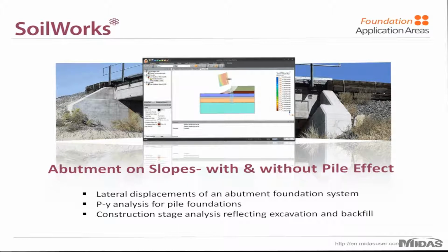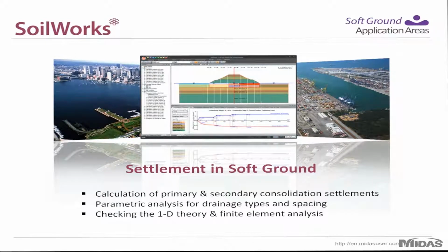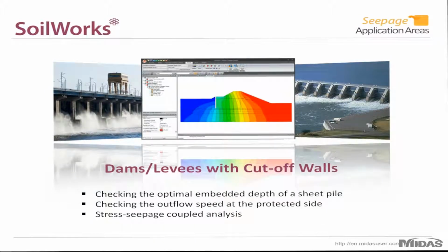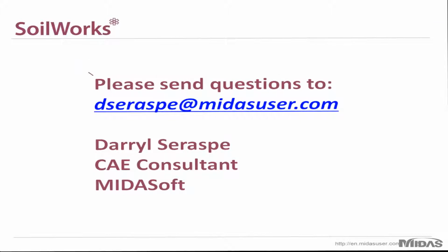Obviously using the foundation module. Abutments on slopes with and without pile effects. So once again, you can intuitively just compare the effects your piles will have on your slope. Group pile behavior, another function of the foundation module. Settlement in soft ground. Obviously, this is for the soft ground module, so you can analyze your consolidation of clay soils over an extended period of time. Dams and levees with cutoff walls. You can analyze the effects of seepage on your dams and your levees. And underground structures. Once again, the tunnel module allows you to analyze these.